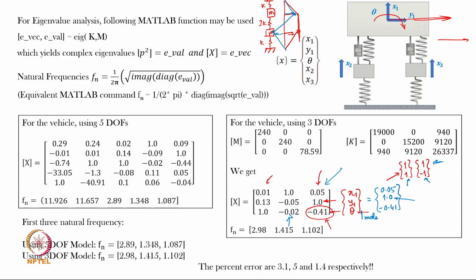Okay. And because the CG here is not assumed to be in the center of the span as a general case, you have a coupled pitch and bounce motion possible. So, which means that if you try to lift the chassis up at the CG, it is going to also tilt, and here the CG position could be such that you still have a vertical x1 motion.